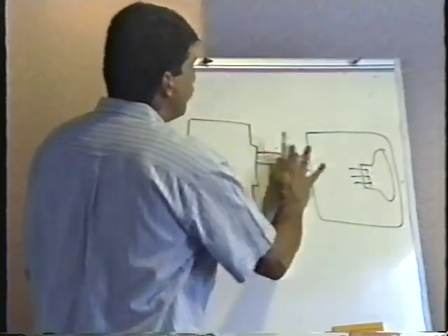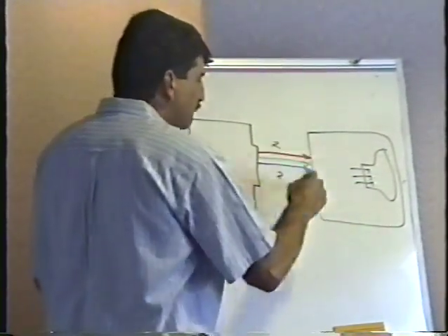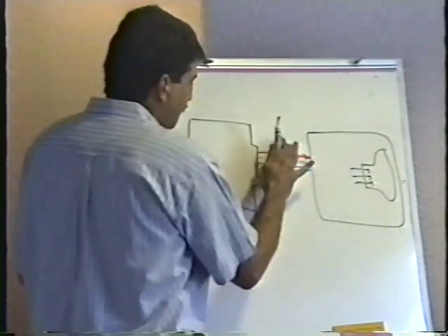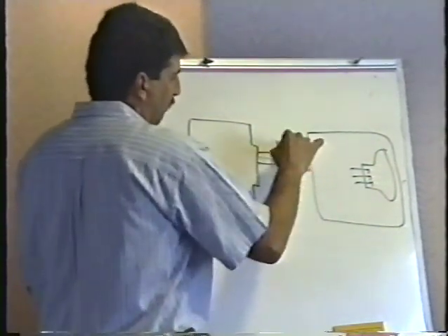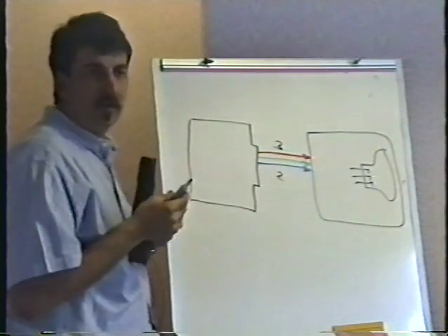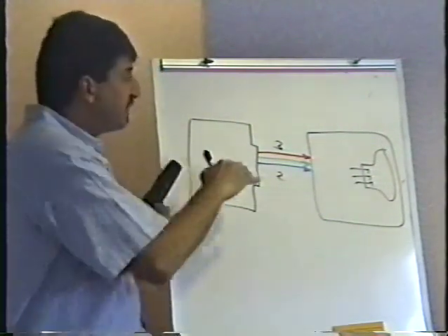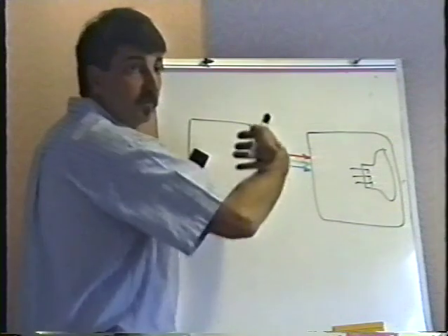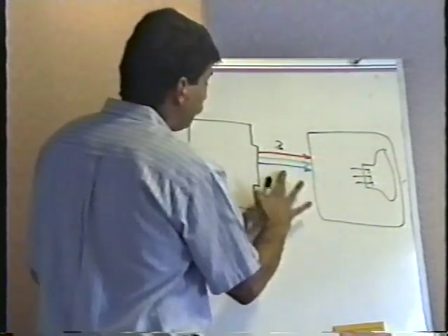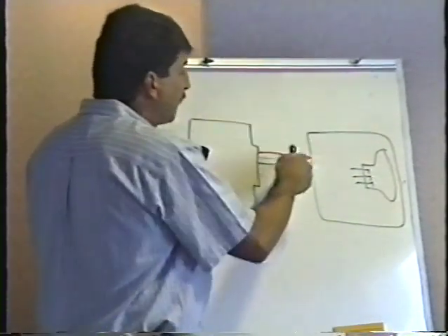If it wants something to be magenta but not as bright, maybe 2 volts out each wire. If it wants something to be magenta but more red than blue, maybe 3 volts out the red and 2 volts out the blue. Just all these are changing voltages. The higher the voltage, the brighter that color is. It's that simple. We do have a name for these signals.